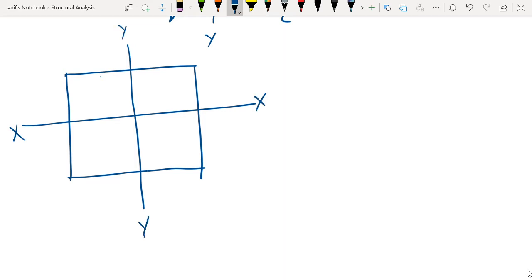So we have 150 each here in mm and 200, 200. If we apply trigonometry, we will see that the eccentricity from the y-axis comes as 40 mm and the eccentricity from the x-axis comes out as 30 mm. And the load is 120 kilonewton. P equals 120 kilonewton.